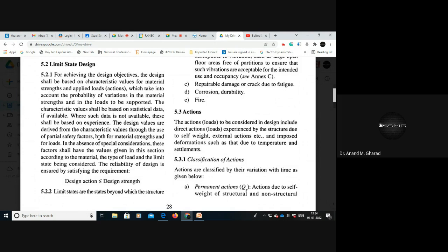Yes, and while identifying that, do we see that all the samples which you have prepared exhibit the same characteristic strength value? It is different, and in order to optimize that, what do we do? We take a number of samples, minimum 30 samples are to be taken, and from that we plot a curve, a bell shaped curve, isn't it?